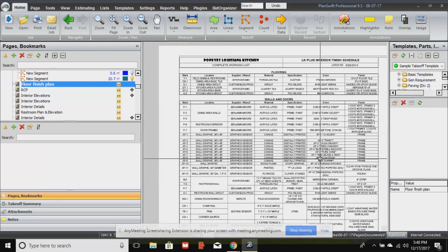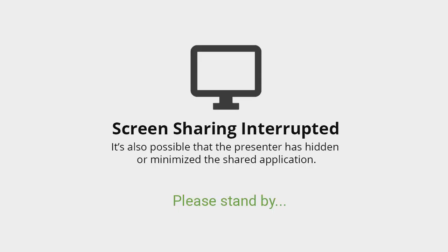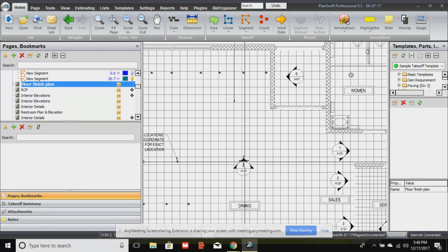Okay, so when you have your interior and exterior elevation views, those are only for finishes. And so they need to tell you what all those abbreviations mean, so they give you the floor and the interior finish schedule. So P1, P2, we know what it means. T1, QT1, we know what all that is. So they give you the floor finish plan, and then all of the interior elevation markers to tell you where to go.